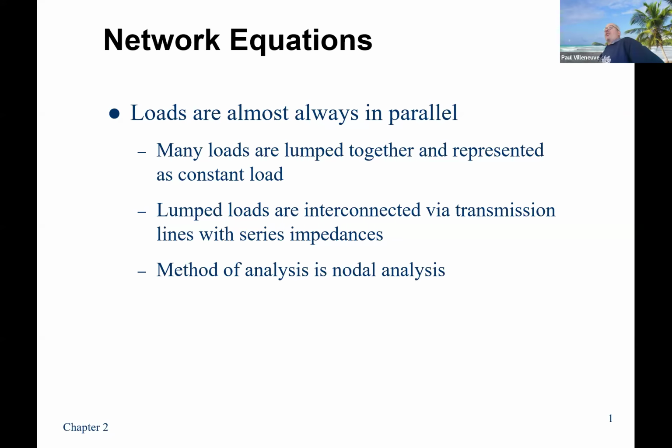The problem with that is once you start solving for the voltages, you have to start substituting in, right? Solve for one variable, for the other variables, substitute that in, and then keep substituting until you're finally left with one equation with one variable in it, and you solve and back calculate that way. That's not practical for a million equations, right? You just can't do it that way. So what they've developed is the approach for Y-bus, which is a very generic way to solve problems where, as long as your system is set up correctly, you don't have to do a lot of additional work, and you definitely don't have to solve simultaneous equations.